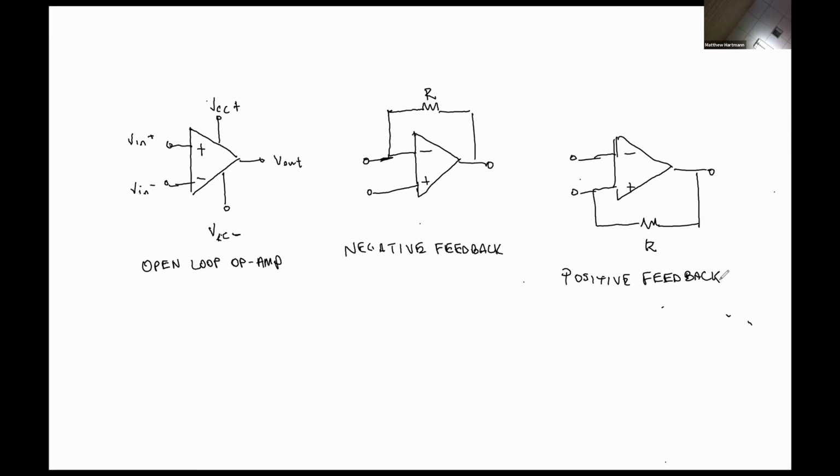The one that says Lecture 3 is positive feedback op-amps, and then Lecture 4 introduces negative feedback op-amps. The ideal op-amp rules that we used in Circuits 1, and you've probably used in your biomed classes, are actually only valid for negative feedback circuits, and we'll explore why that is in this class.